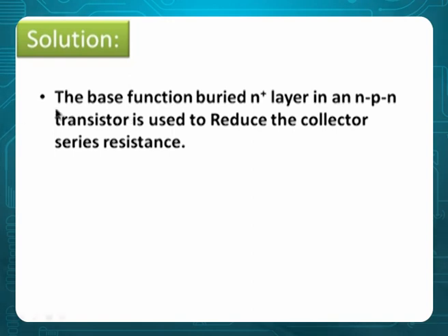The base function of the buried n plus layer in an NPN transistor is to reduce the collector series resistor. Collector series resistor means the option is B. So that is why it is used. We can reduce the collector series resistance.